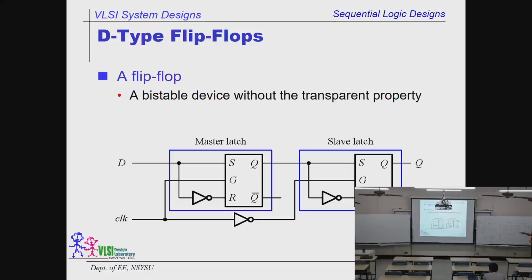All right. So this operation is considered as a sandbox. It is called a master-slave D flip-flop. And at what moment is the transition finished? At what time is the entire operation done? It only happened in this edge. This is the falling edge. So from time to time, this kind of design, master-slave, is also considered as an edge trigger flip-flop.